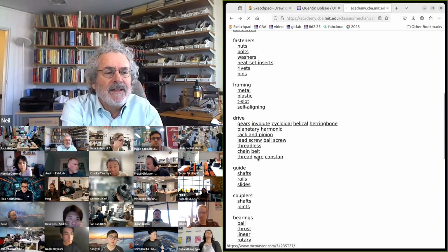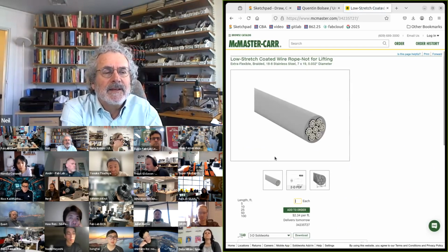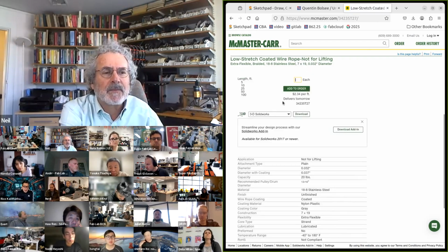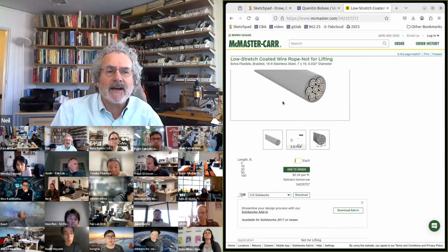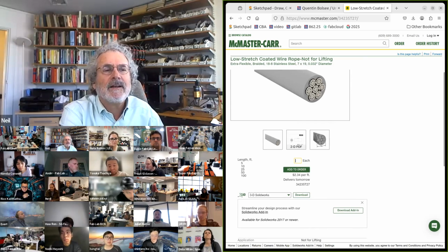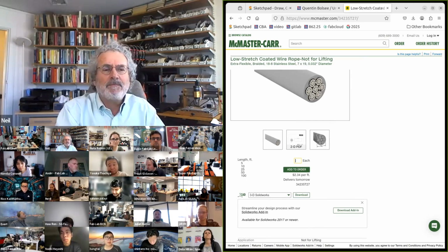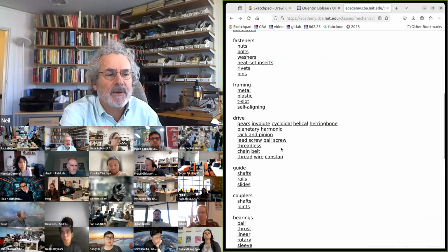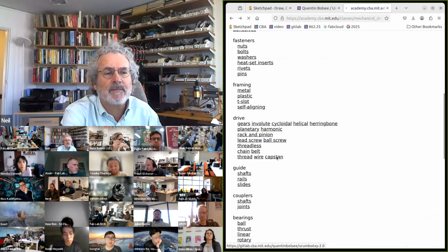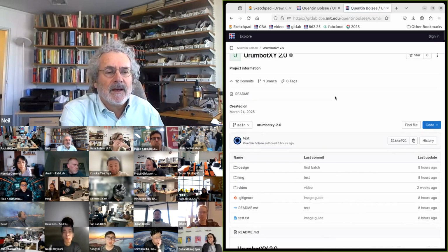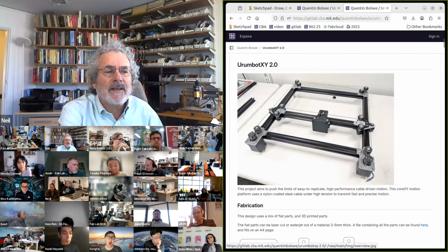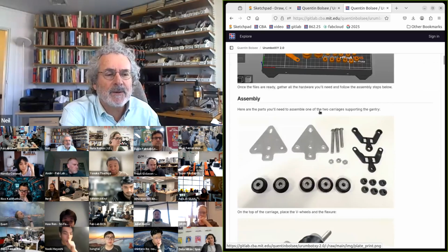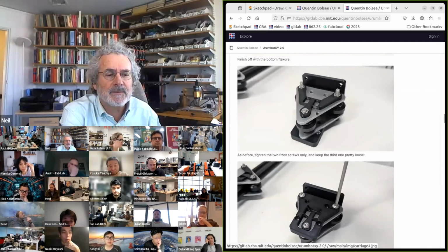And then a neat way that I like for machine building is this, which looks like a metal thread. It's kind of like the inside of an electrical wire, and it's designed to be bendy but stiff. You can't stretch it at all. And so, coming back to this example, what's going on here is what's called a capstan drive. So if we come down to here,